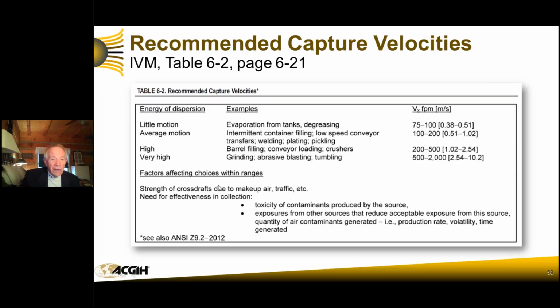This is really good. The strength of the cross draft due to makeup air or traffic. Is this an area where they are going to be using cooling fans? Is there walking traffic? You saw what somebody walking by that hood did to it. We needed to jump that capture velocity up where that guy was walking by the front of the hood, if that's going to be something that's going to be happening periodically.